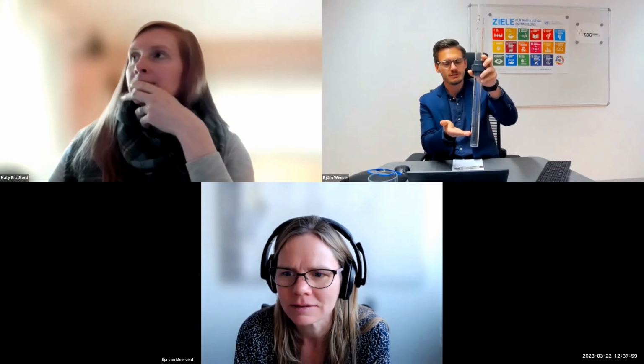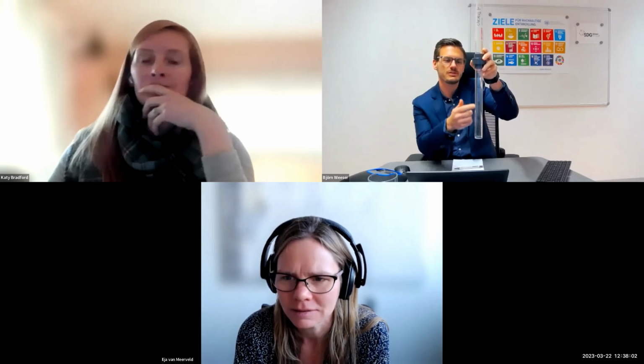Yeah, sure. The nice thing is I saw the questions while the talk was ongoing, so I brought one. We are using this kind of turbidity tube, so they're actually commercially available. Unfortunately, in Europe, we had to import them from the UK. Basically there's a very small mark inside. So you look from the top and start filling up the water, and this mark disappears at a certain level. And this level is written on the tube on the side. So this is calibrated in turbidity units, basically. You can directly read the value and say, okay, if you fill up the water until here, it's like 50 turbidity units, 25, 15, 10, and so on. It's a really simple method to use.